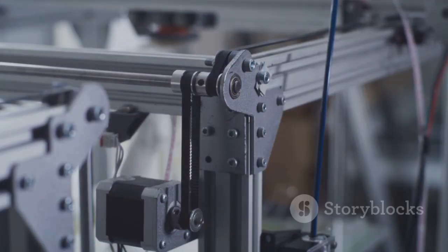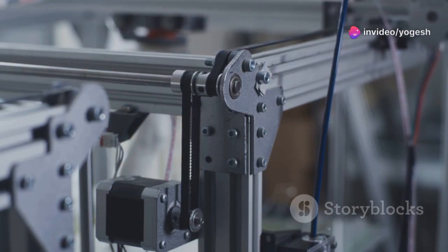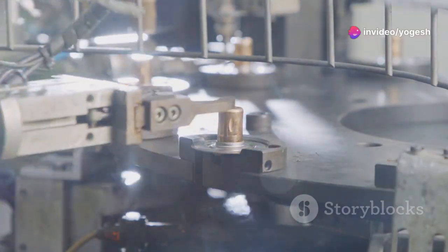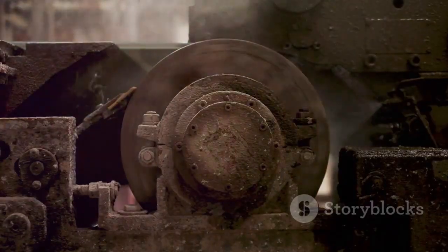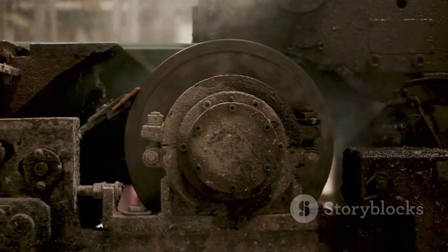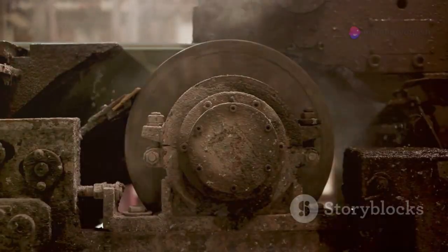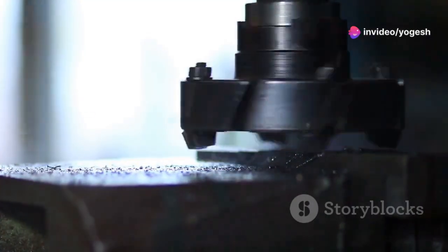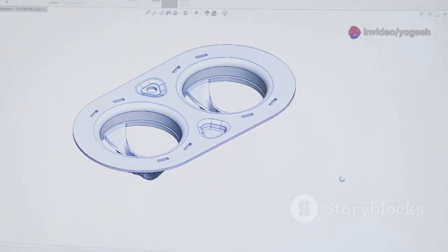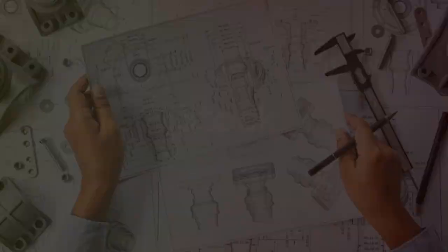Good concentricity also makes assembly easy. Parts fit together smoothly and reliably. It's essential for automated assembly lines, where precision is non-negotiable. Ultimately, controlling concentricity boosts reliability, reduces wear, and extends product life. Whether it's a drill bit or a gearbox, concentricity keeps everything running true. It's a fundamental requirement for robust, dependable engineering.